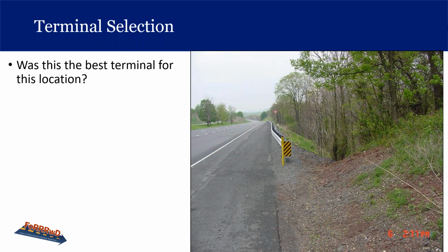And so there is a catalog of end treatments that you can find if you go to the FHWA Office of Safety and then go to Roadway Departure Countermeasures, and then they have road terminals. And it's got, like I said, a catalog of different end treatments, but the buried in the back slope would be definitely better than what's there in the picture.